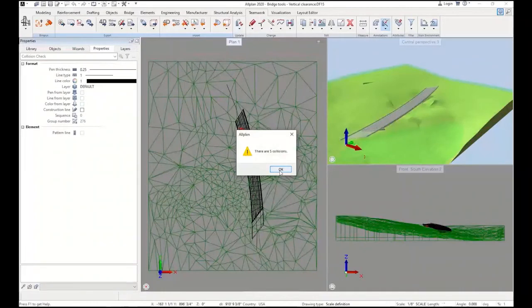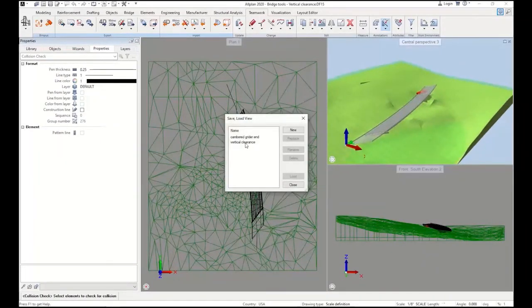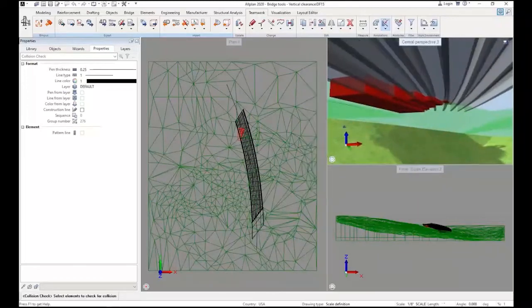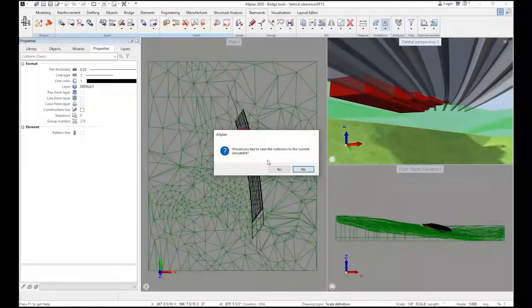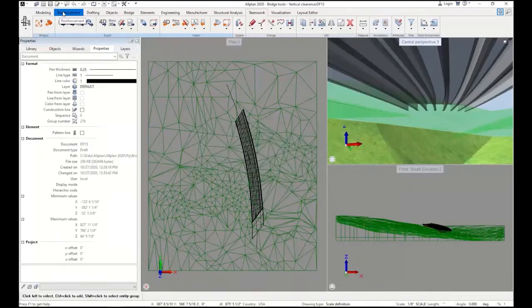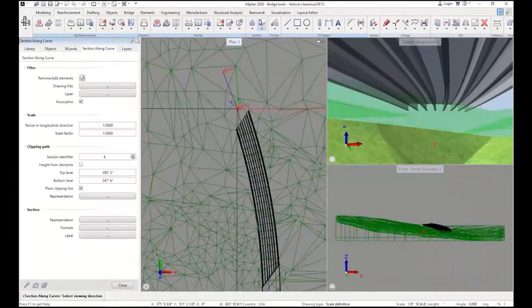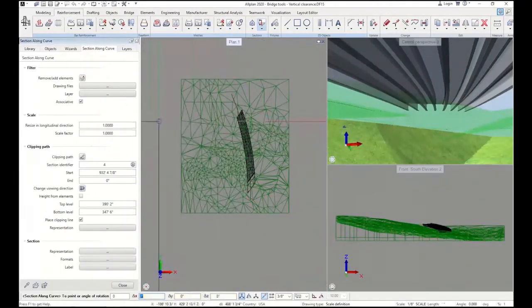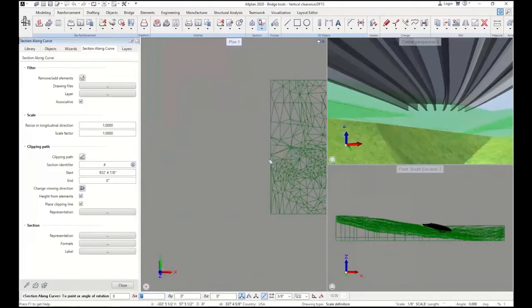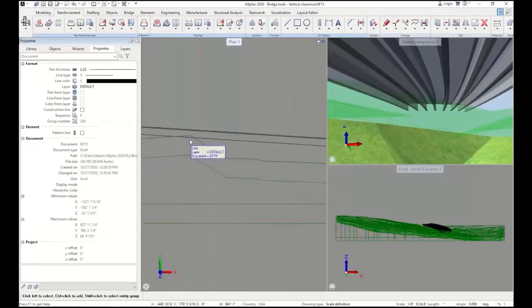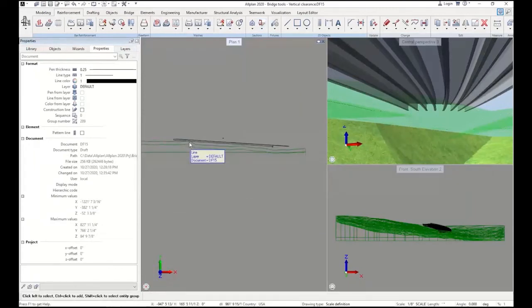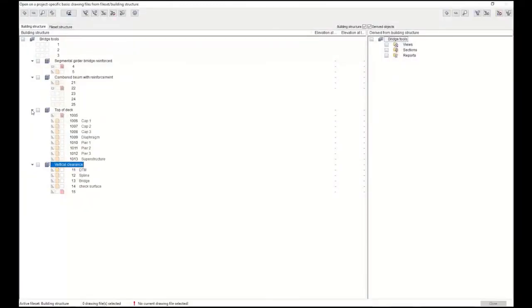And you're going to see that it's not only showing me how many collisions, but it's also going to show me exactly where they're at, for how long they occur, over which points. I can save these to the document if there's somebody else's problem to deal with, or I can take care of them right now. Another thing we can do in ALLPLAN also is always cut a section along a curve. And so this will give you a true cut along that curve. It could even be a jagged curve here. And I can do a visual manual inspection and just dimension this myself as well. So you can still use your tried and true methods and also employ the computer to do quite a bit of work for you that you manually do normally.